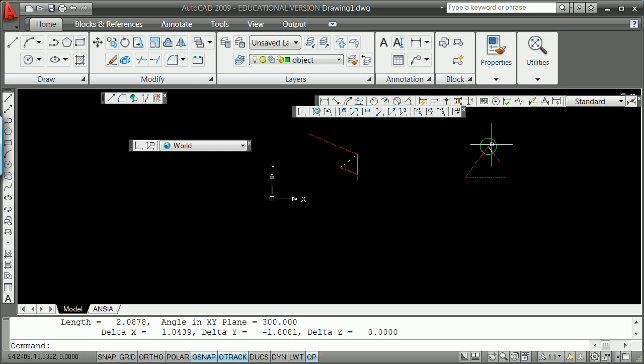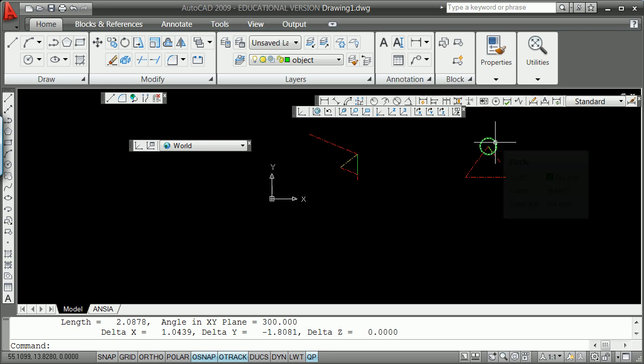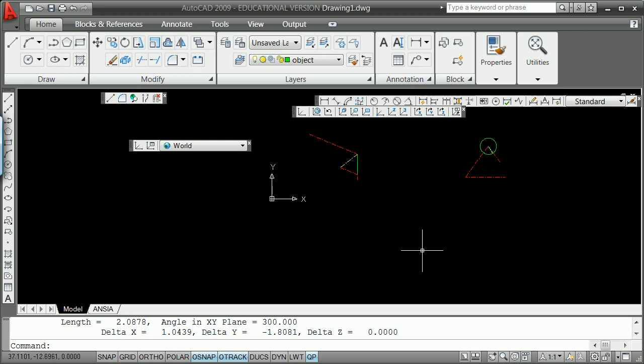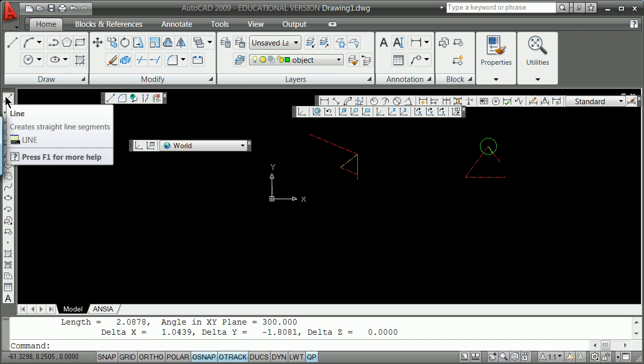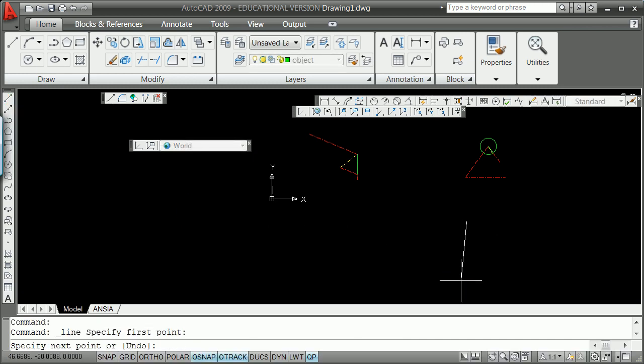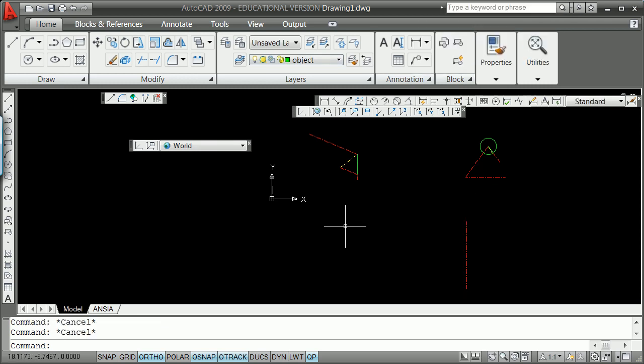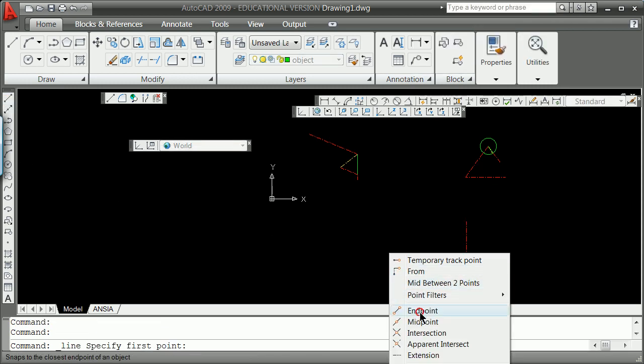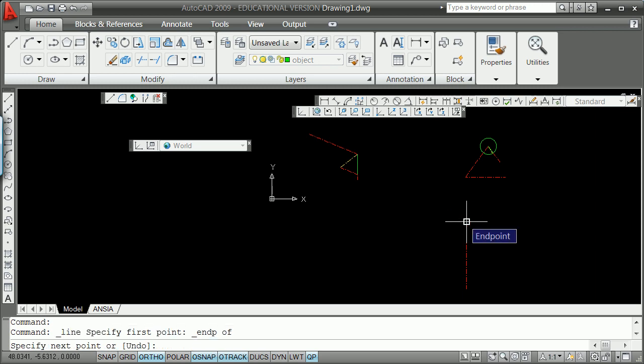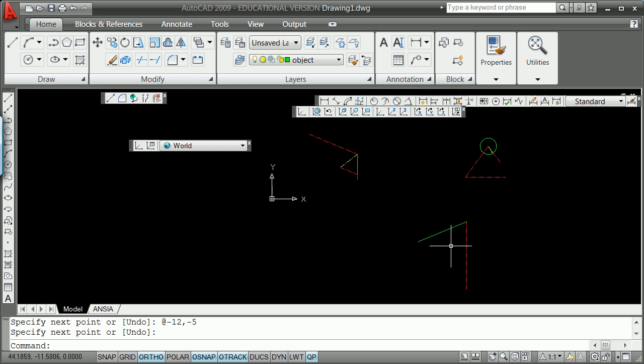That is problem 2.55. 2.56, again, it's geometry. We should have enough time just to do it if we're really good about drafting. We're going to go down. We've got F8 on. Right, we want that to be on layer centerline, or something that kind of fades to the back. We have a line from the end point here at minus 12, minus 5, and the other one is at 30 degrees, which is 30 degrees from vertical.